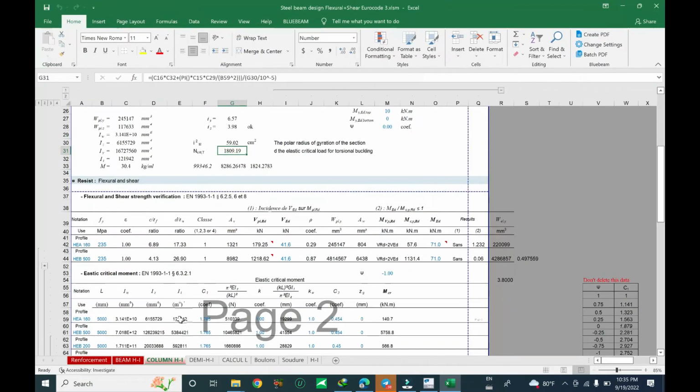So when you apply the bracing, the intermediate bracing, you should apply it within this length. You can apply 1200 millimeter or less than 1382. Now let me set it to 1100 millimeter. You should apply it below the limiting unbraced length to prevent lateral torsional buckling from occurring in the beam. Distance between flange centroids. Yes, limiting unbraced length. This is the moment at the quarter of the beam segment: MA, MB, MC, and Mmax.